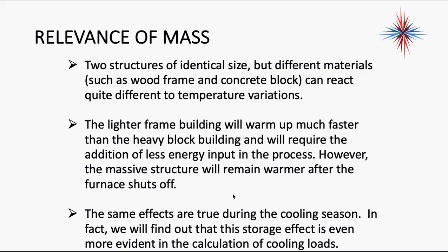So, we have two structures of identical size, but different materials. Okay, the difference between a wood frame and a concrete block, they can react quite differently to temperature variations. The lighter frame building will warm up much faster than the heavier block building, and require the addition of less energy input to the process. However, the massive structure will remain warmer after the furnace shuts off. The same is in effect during the cooling season. Okay, this storage will be more evident in the calculation of cooling loads.